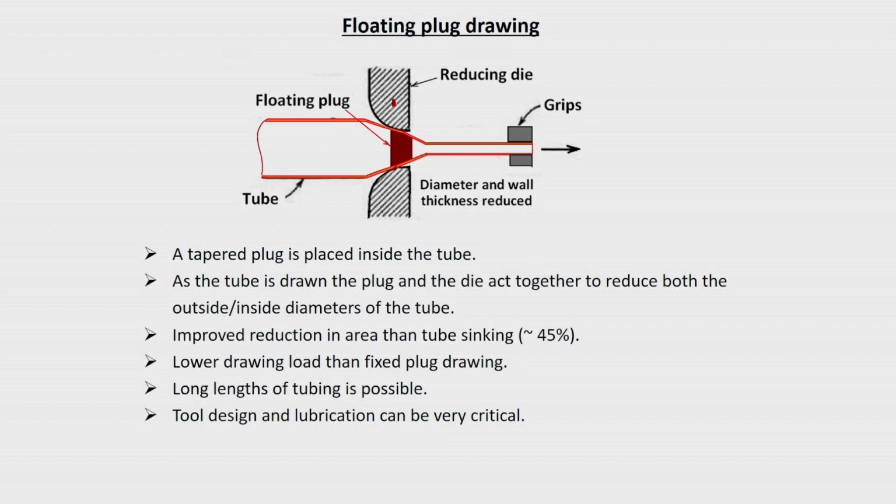You need to have a very clear-cut design, and the tool design is very important here, and that also depends upon the type of lubricant, the surface finish of the die material, and the surface finish of your workpiece material, all those things. A very complex analysis is required for these purposes, but anyway you are going to get it.